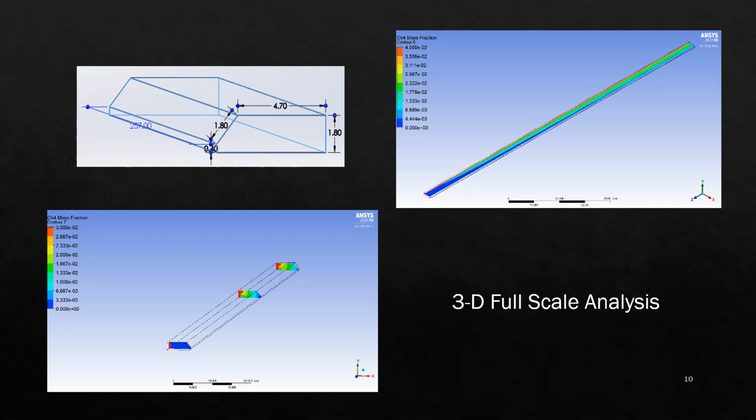So one of the things I went back to look into as far as the modeling goes was how I define these parameters with that species transport. Like I said, I wasn't entirely sure at first, since it's mainly there to model the combustion and contains all these species. I had to make sure that the air was actually O2 and N2, because I wasn't exactly sure what concentrations or percentages, if it was 70 and 30 or 60-40, of O2, N2.